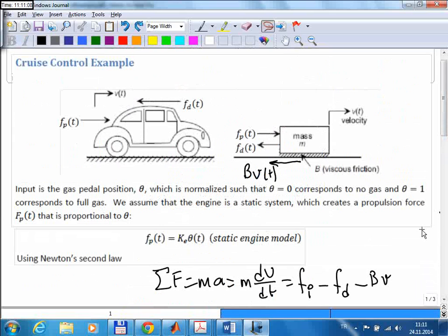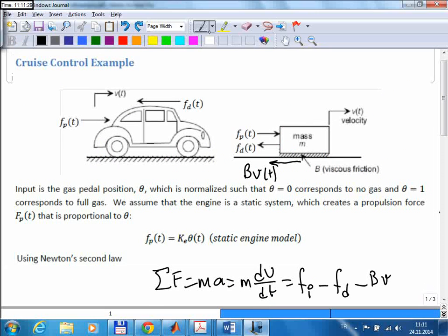So obviously there are additional forces. For example, you can include aerodynamic drag force, but we know that drag force is proportional with the square of the speed, right? If you consider the aerodynamic drag force, for example, that is not included here. Well, the main reason is we cannot really use a square term in our equation, because if you try to include the aerodynamic drag force, that needs to be something like 1 over 2 rho v squared S times Cd, right? So it needs to be proportional with this square of the speed.